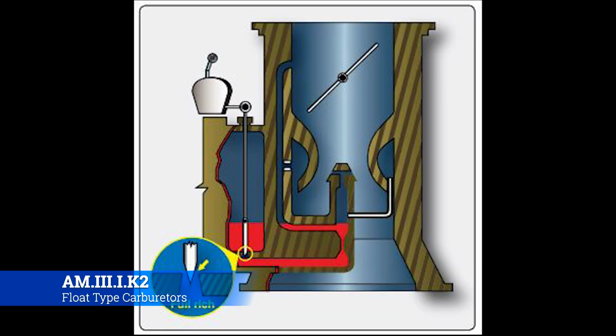Okay, so let's talk about the mixture. The mixture, just like we were talking about earlier, has to be adjusted per the altitude that you're operating at. And what that effectively will do is allow certain amounts of fuel to come into the jet. Now, keep in mind your carburetor needles, your air bleed needles, all the jets, everything is going to be kind of a steady state for ground operations, primarily set at idle, and then tested at max power. However, the mixture has to get adjusted as you climb in altitude.